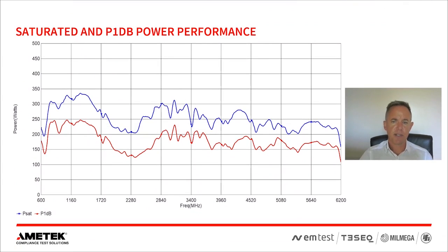As mentioned earlier, most solid-state amplifier datasheets list two types of output power: saturated power and P1 dB power. It's very important to pay attention to these specs in relation to your application. For instance, if you require linear performance from your amplifier, then only the P1 dB power should be considered. In this example, this would be the red curve, which indicates the maximum amount of power the amplifier can produce when the gain is in error by 1 dB for any given frequency. If the datasheet does not list the P1 dB performance, then this should be considered, as it may not meet your application requirements.